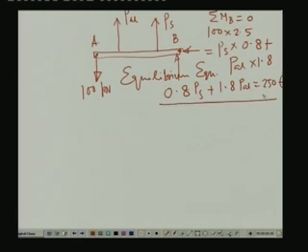Now, from the compatibility, since this load is acting at this end and this is the pinned end, the bar will move in this particular form, and this will move in the form of a circle with the center at this particular point. Now, this being a small deformation, we consider this arc as a straight length, hence this is a triangular form. So, at these locations this bar will undergo deformation, and let us call this deformation delta S and the deformation here delta aluminum.